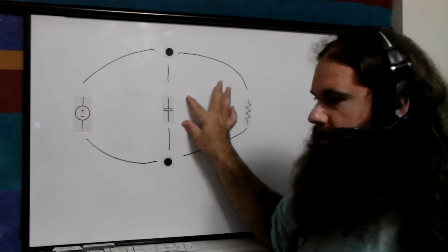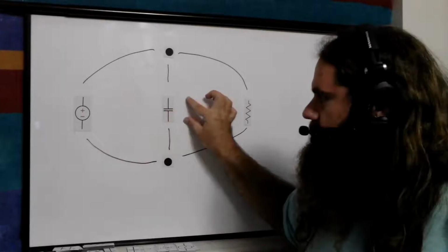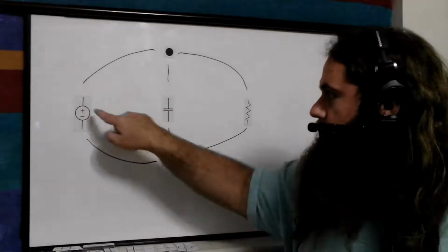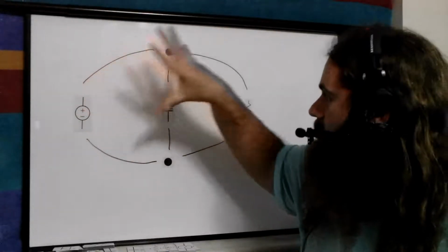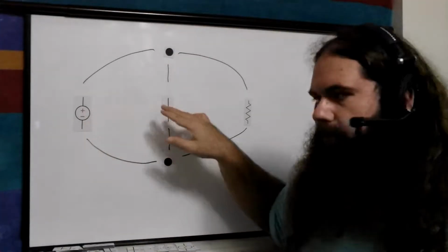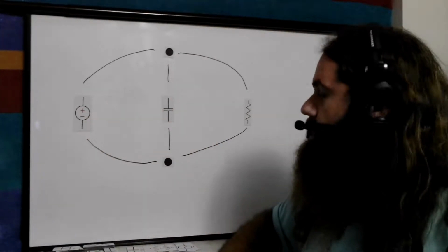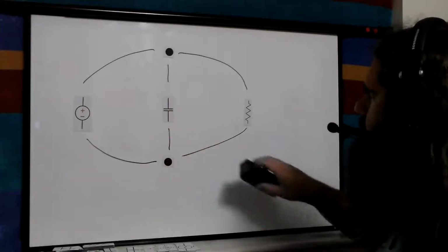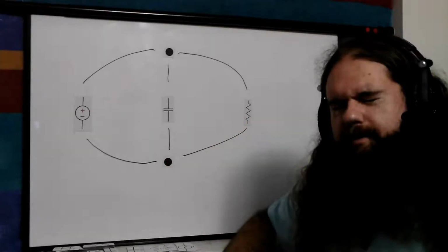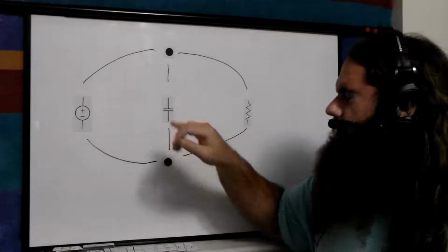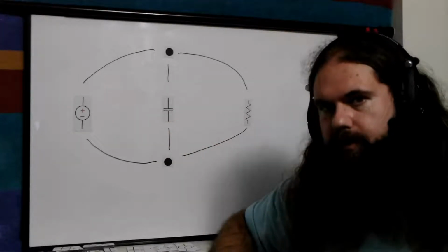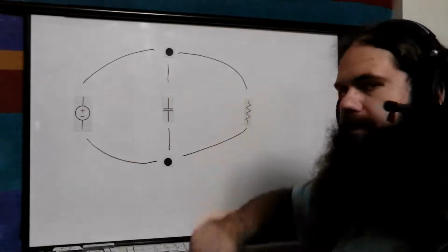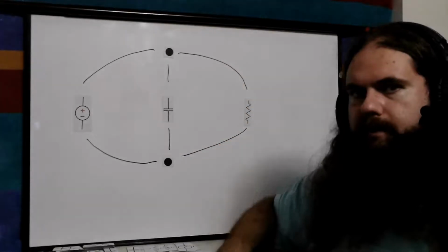But the more charged this becomes, let's say this is 5 volts. Let's say this is charged to 4 volts, right? The difference is only 1 volt now, because it was 5 to 0, so that's a full 5 volts, so it's all going right in there. But 5 to 4, that's only 1 volt difference. So there's plenty left over. So as the capacitor is charging more and more slowly, more of the current is making it through to the resistor. And once the capacitor is essentially fully charged, it's just sitting there, charged but doing nothing, and it's as if it's not even there. And you've just got your power supply and a resistor.